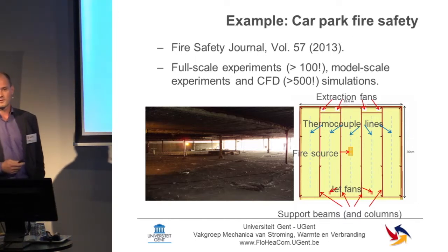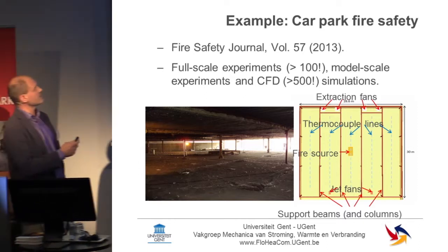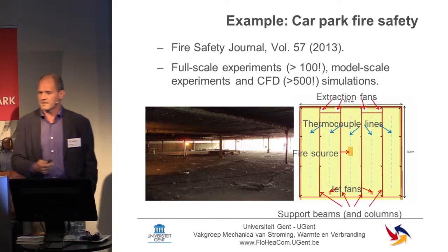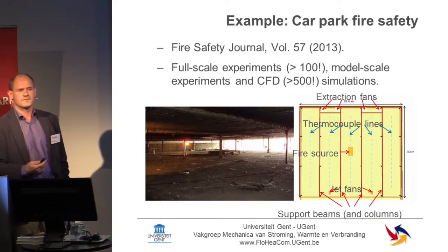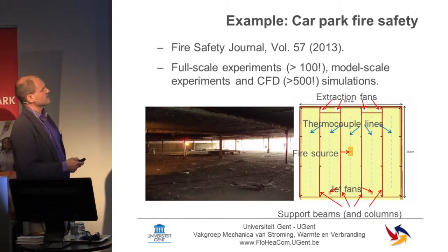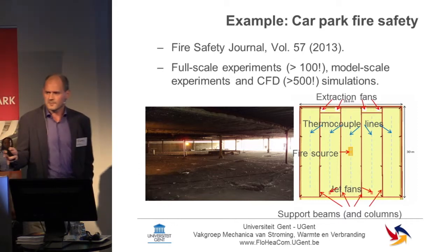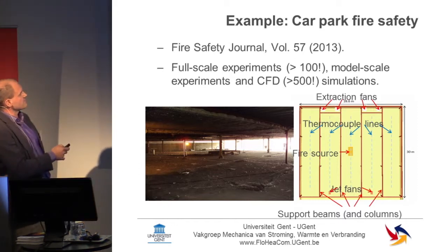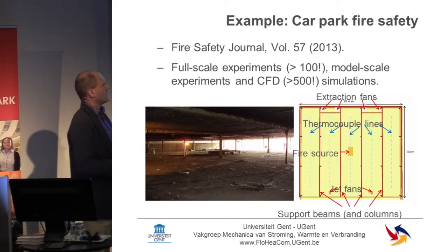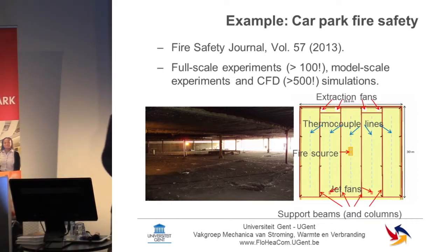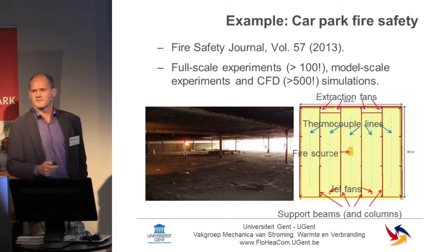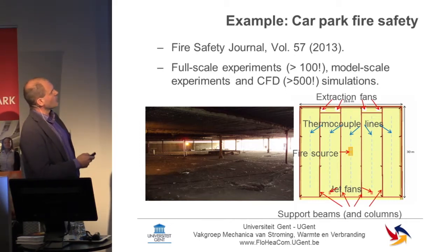Why would I venture to say this? Because a couple of years ago, and some of you will have seen this in Ghent, we carried out a study into fire safety in parking garages, particularly in the ventilation of these parking garages. And we did this with a fire seat that had been predefined. And we also set fire to vehicles, but well, that's something else. We have a well-controlled liquid fire with a pump that gave us a certain power, so we knew exactly what the heat was of the fire, so we didn't have too many uncertainties here.